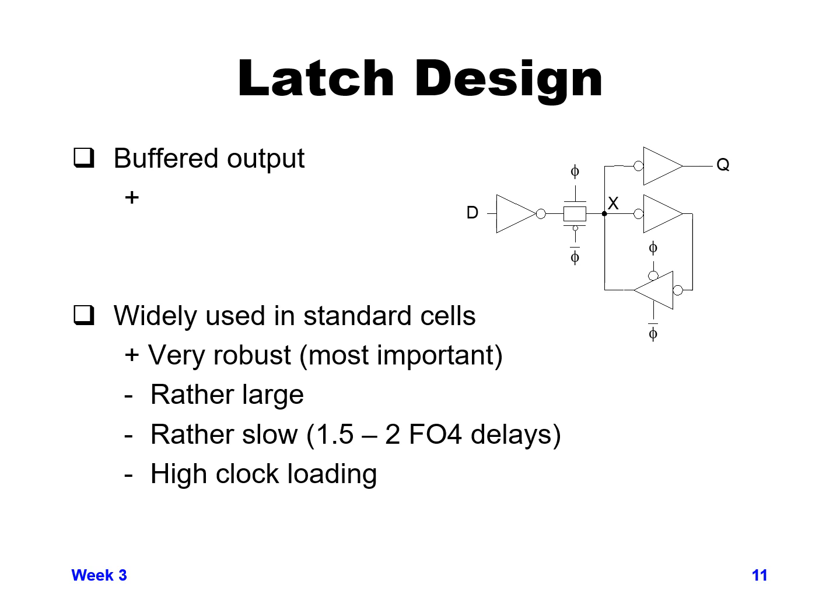Continuing on with yet another variation of the latch design that we've been working on, we can add an additional buffered output. The benefit that this buffered output has is if you have any noise on your output Q, so Q is going out and driving maybe multiple other receivers, if those receivers try to backdrive any noise onto your latch, the buffer will not allow anything to go back and interfere with the state node X.